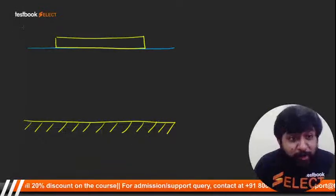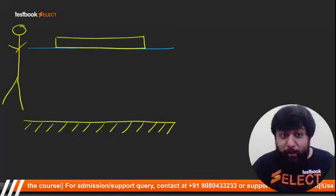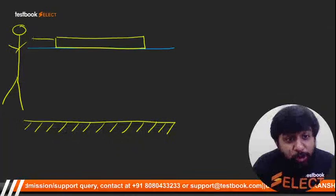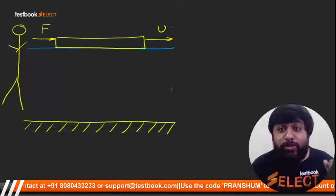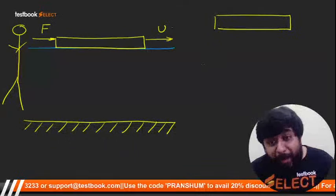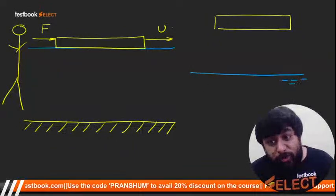So for fluid what we said, Newton was performing an experiment, right? And Newton said when I push the plate ahead with a constant force, I will observe that the plate is moving with a constant speed. So what will happen? Between the plate and the surface of water, there will be a shear force, right?